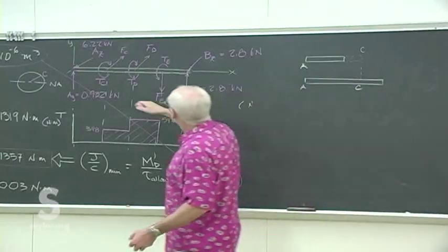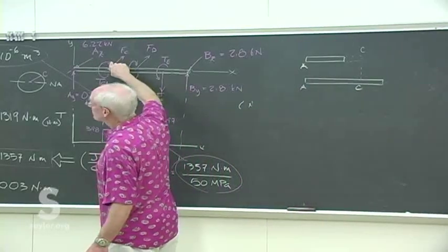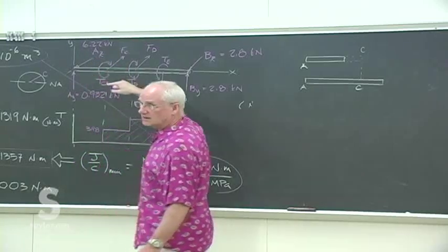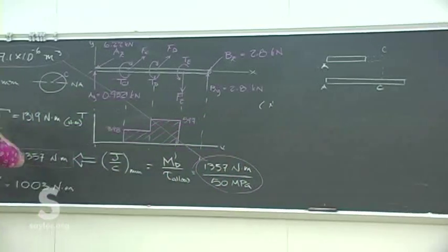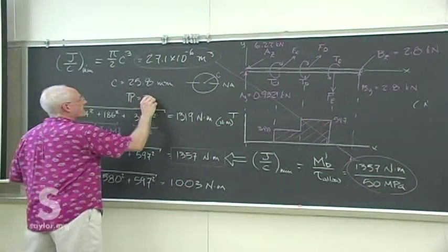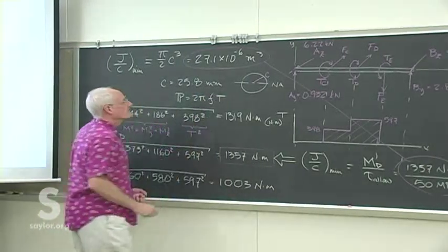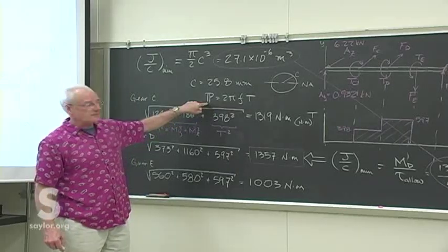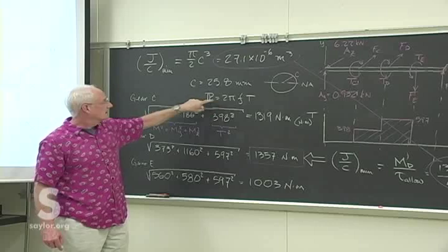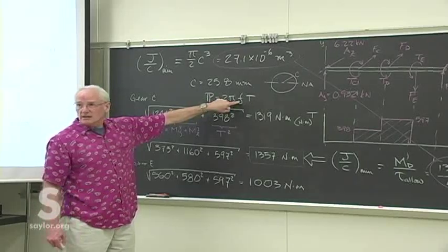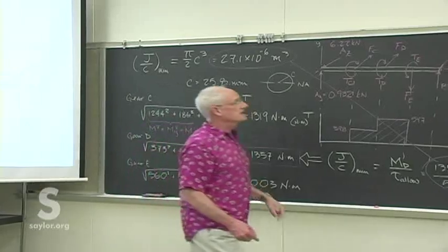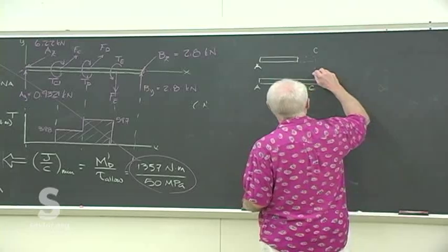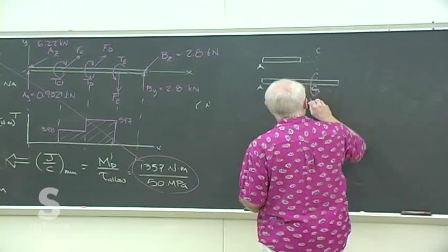and the torsion due to point C, and remember that's using the amount of power taken off there and the frequency, and we can find T there. Just do that for point C. We know how much power was coming off. I think it was 10 kilowatts. The frequency, I think, was 8 hertz. Remember, watch your units on these. So it means that 20 kilowatts for that.